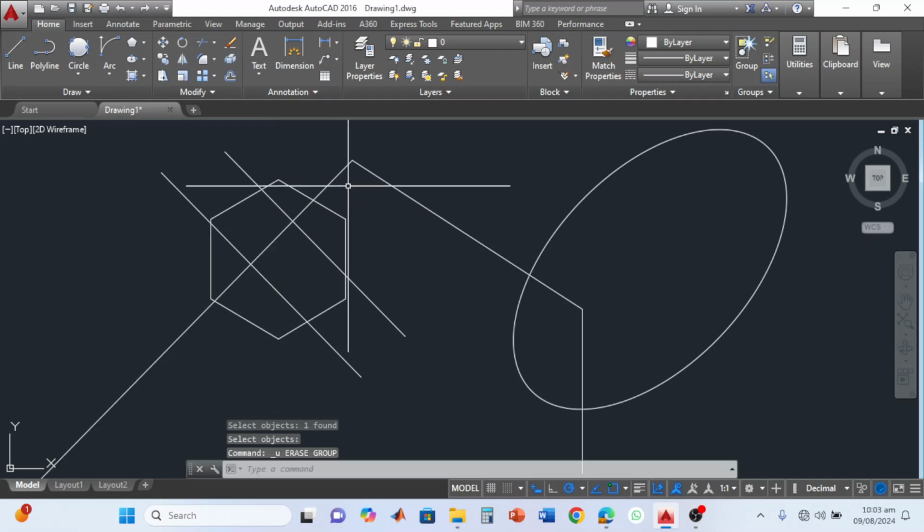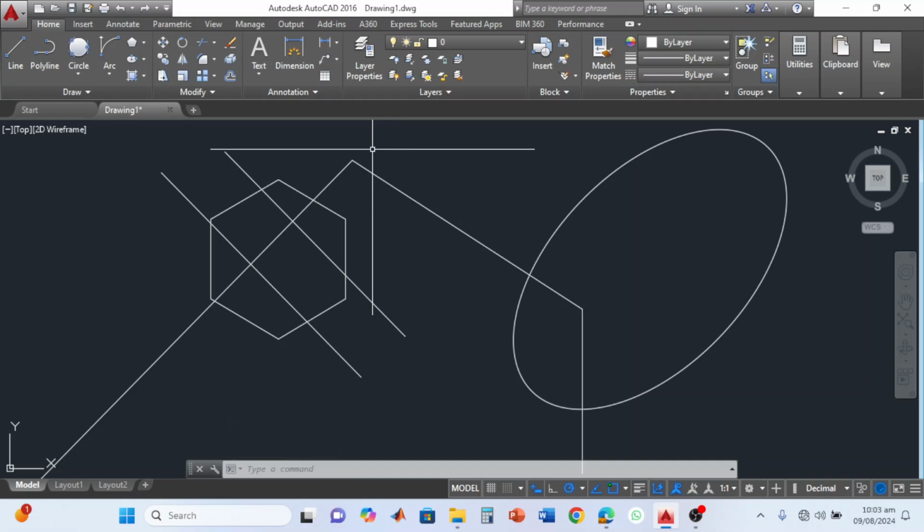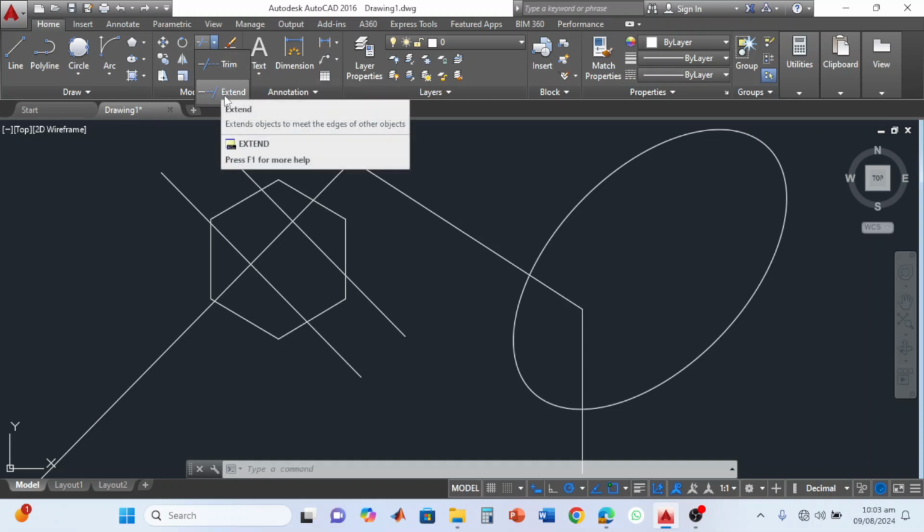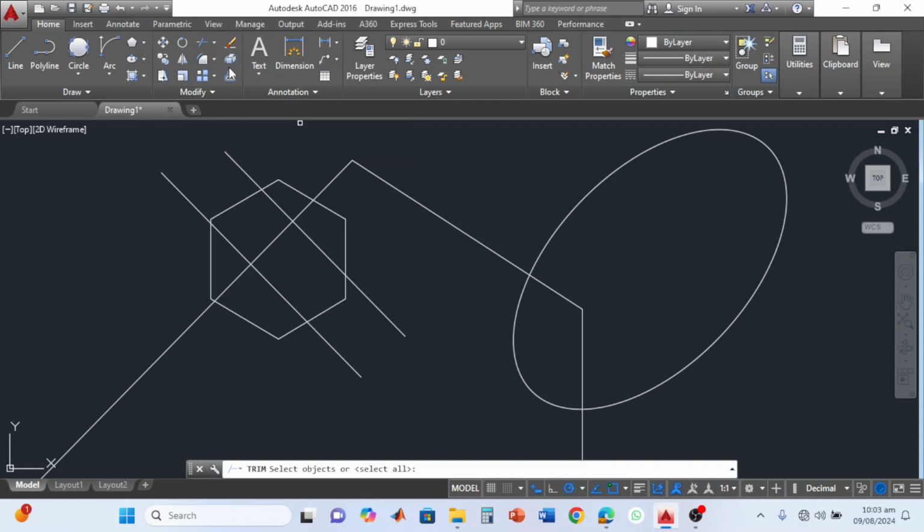The trim tool. Again, in the trim tool there is some variation. We have two tools available. The first is trim. Select the trim tool, and now we have a selection toolbar. In order to trim, we don't have to select only one object, but the adjacent objects. At least three objects are to be selected: the one that we want to erase, and the respective objects which are the two boundaries.